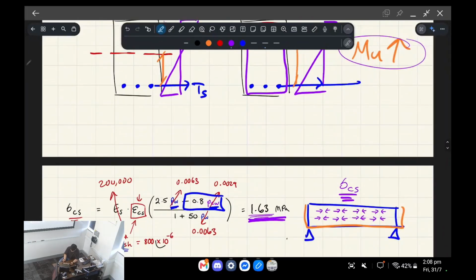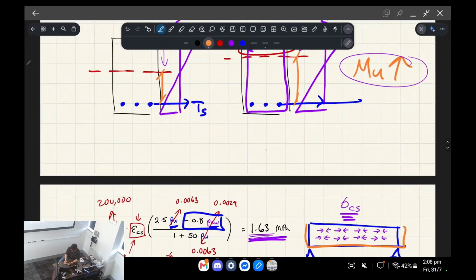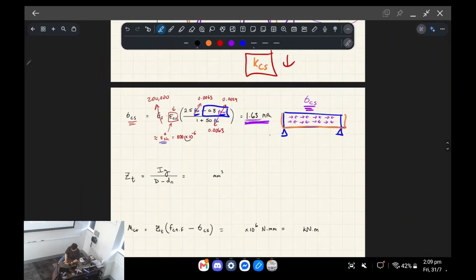It will reduce your shrinkage stress, and later you'll see something called KCS, which is a creep shrinkage factor, and basically it exaggerates your long-term deflection. It will decrease this if you have compressive reinforcement. So compressive reinforcement does about 5 or 6 different things, right? Incredibly useful. Okay, sorry, tangent.